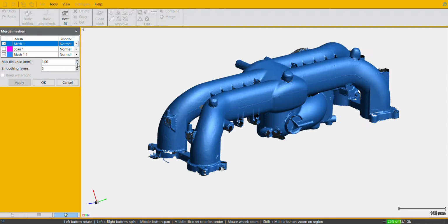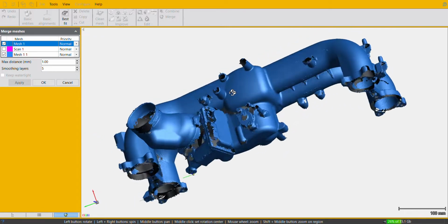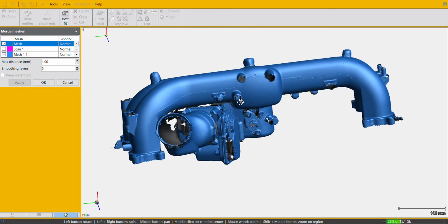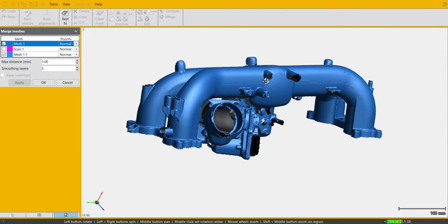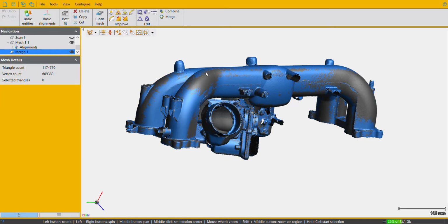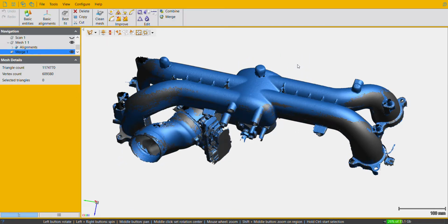Control-Z doesn't really work with a lot of the features on this. So note, it's usually a two-step confirmation. Looking around, it looks good. Got some pyramids, some breaks. There are holes in the scan, but small things that were there I don't need. Either that or I knew it was reflective surfaces it wasn't going to pick up real well. Looks good to me. And from this point, you have one aligned merge mesh that I can export as an STL or various other options.